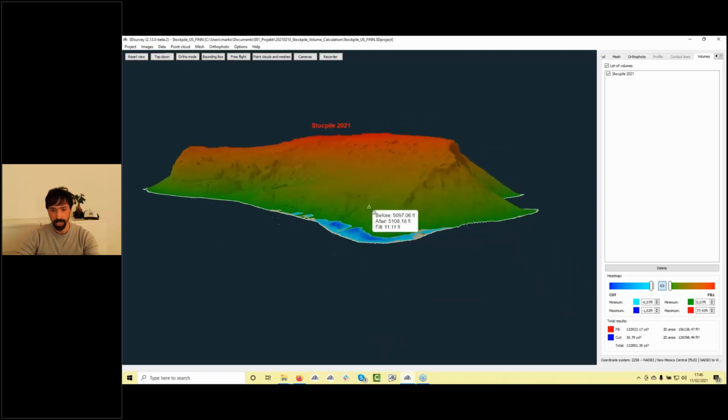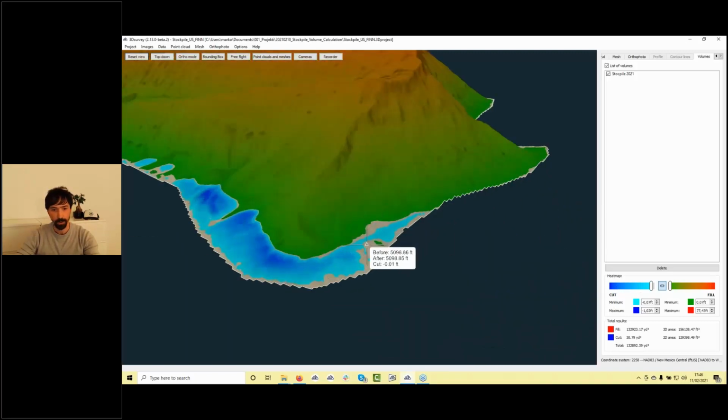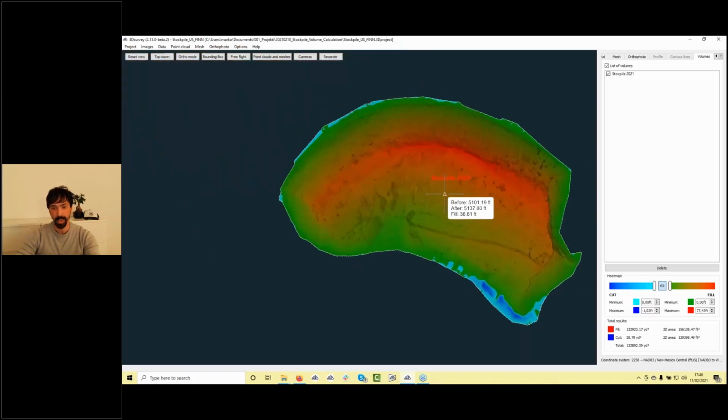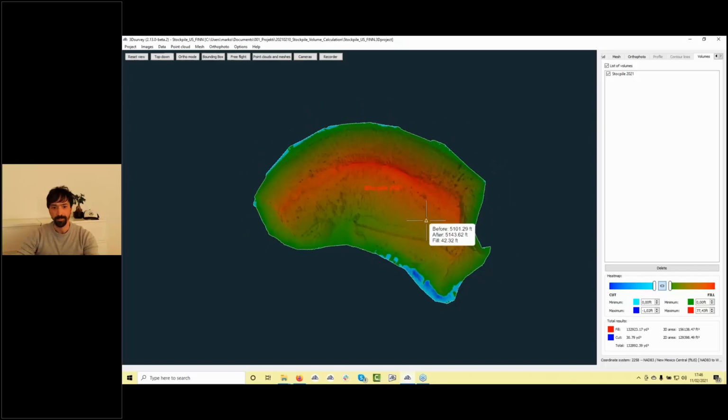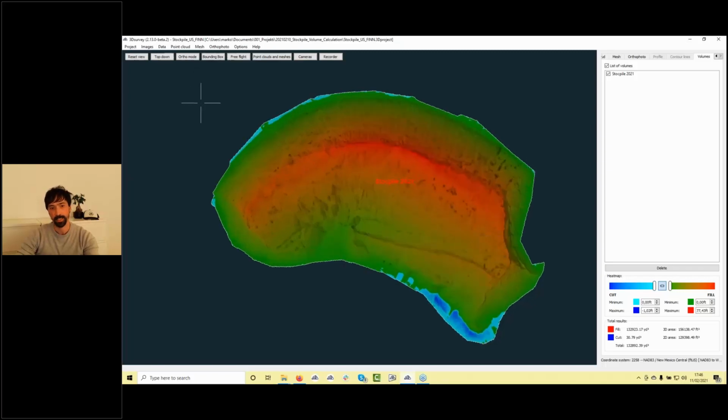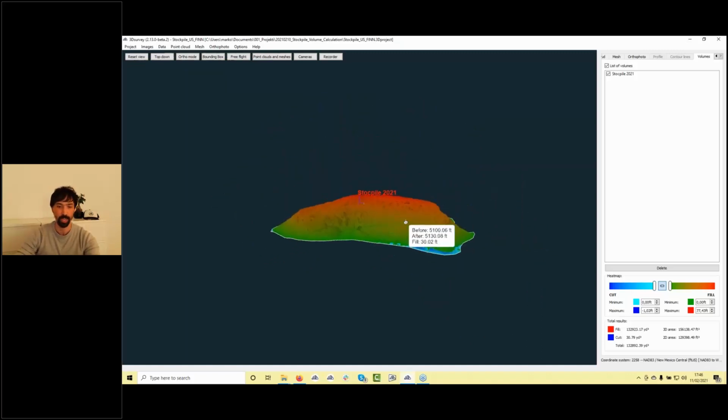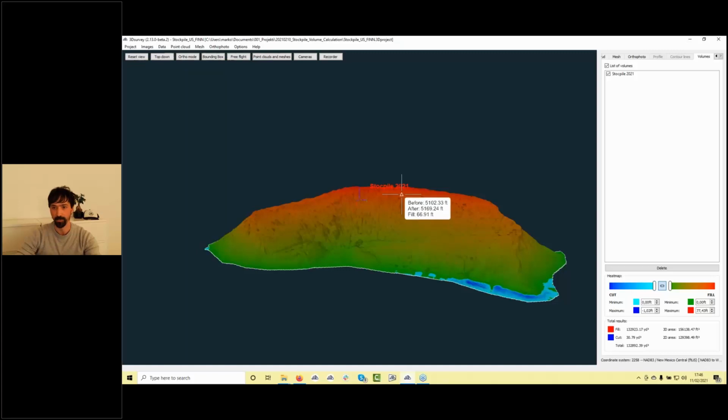Then we have some kind of buffer zones. So here where we have a realistic color, this is between minus 0.07 feet and plus 0.07 feet. So here no change was done. Actually the two surfaces cross together. We can increase this or lower it, anything like that. And then what you can do with this, you can save this as a quick report, but I would like to show you this a bit later after we calculate also profile lines for this stockpile.